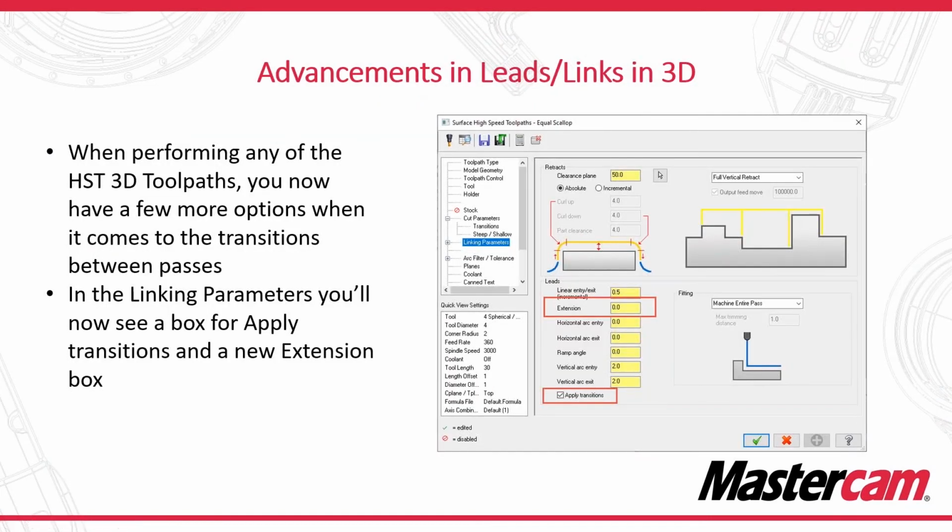All right, advancements in leads and links inside our 3D toolpaths. This one, I'm not going to lie, is tough to explain. When I'm talking about leads and links in between our toolpath, I'm talking about a transition between our toolpath slices, so each one of our stepovers. What we have now is the ability to take what we have in our leads, how we're entering and exiting the part, and maneuver that into how we're transitioning in between our cuts.